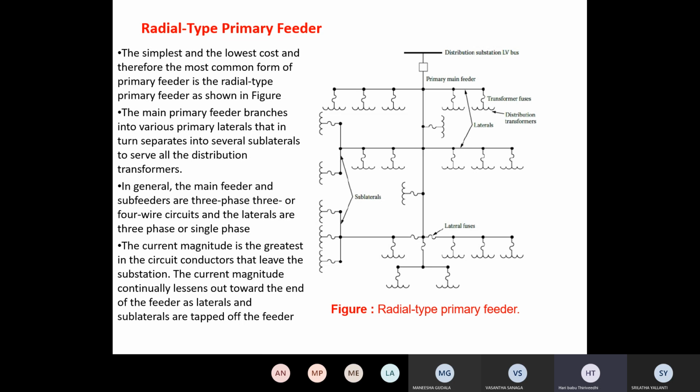The size of the feeder is also reduced. However, the permissible voltage regulation restricts any feeder size. To maintain the voltage fluctuations within plus or minus 6%, that's why you have to resize the feeder also.